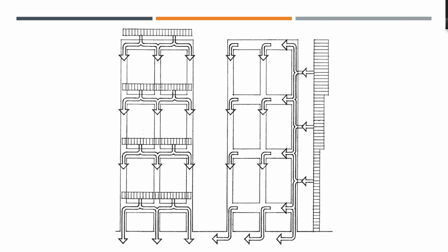And then lateral load. So this is interesting now. If the lateral load is wind, wind will be applied first to the walls. From the wall, it will go to the column. From the column, it will go to the floors and all the way down and onto the foundation. During this process, it will deform the building and so on. But it will start with the walls, cladding or glass, from glass to the columns and floor, from that to the vertical system. So gravity load will flow like this, and lateral load will flow something like this.